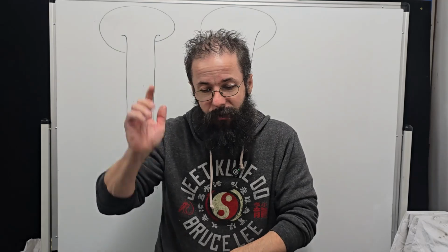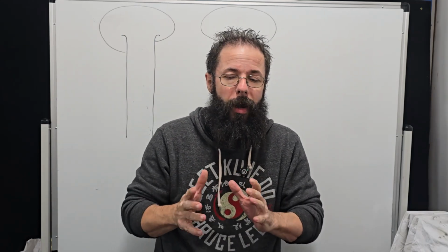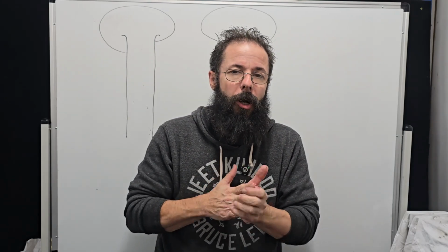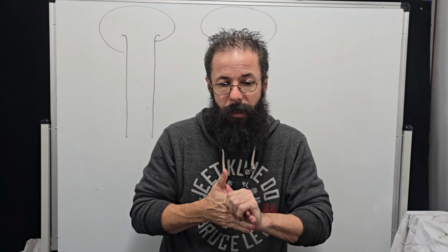But I wanted to explain a couple of the problems I see when people are just testing a parallel pipe, because it really is easy to test induction with a parallel pipe because we can just cut it down, weld it back up, get in there, die grind it, most people just deburr it, hope for the best. And we can do that on the dyno really, really quickly, but there's a few problems that come into that, and I'll try and break it down on the board why it can lead you up the garden path. And there's a couple of telltale signs there, even in the dyno graph with harmonics and stuff like that, that will tell you, yeah, it's coming into tune, but we're actually choking velocity.